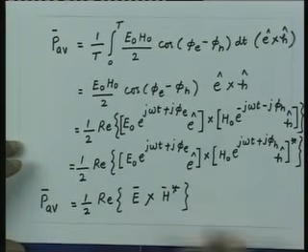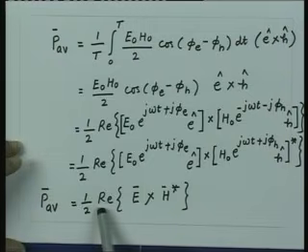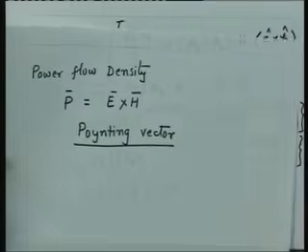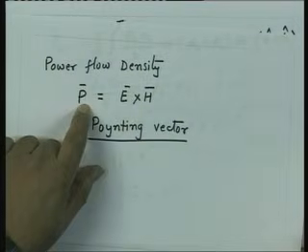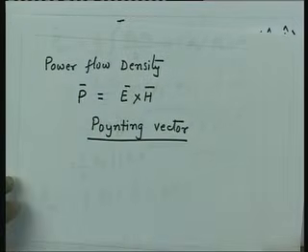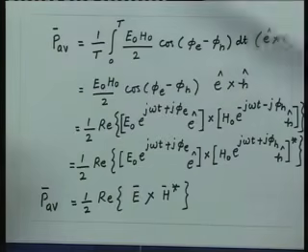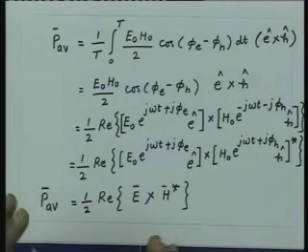Now, this quantity is a real quantity as we are taking a real function of this. So, all those problems which we had with the instantaneous power flow, which could either become complex depending upon the phase difference between them, have now been taken care of, and also it tells me now the overall power flow which will be associated with these fields at their particular location.